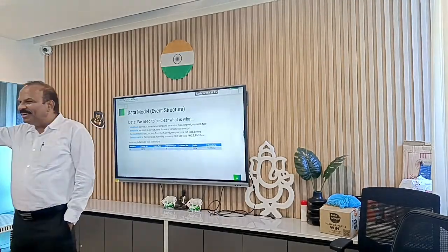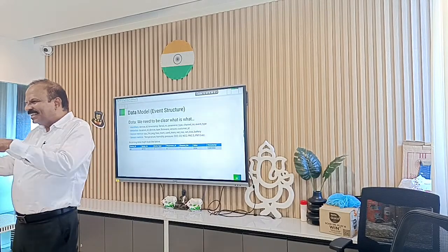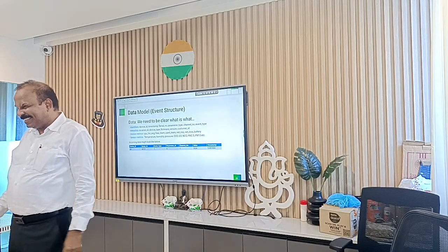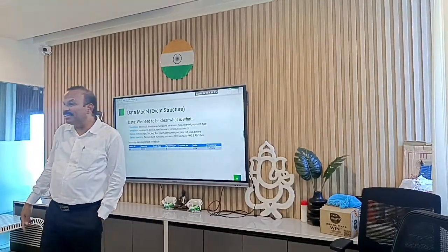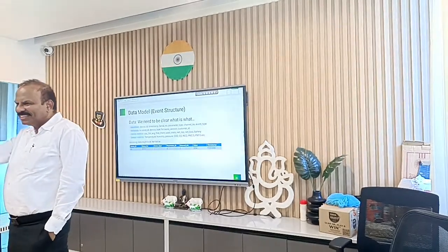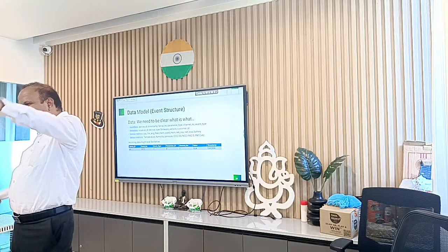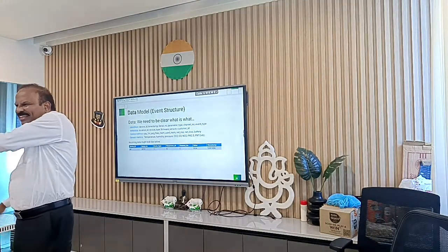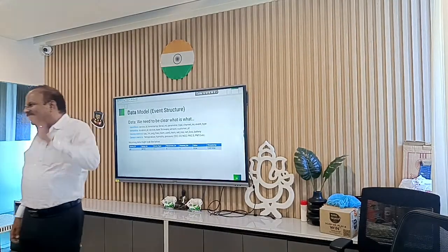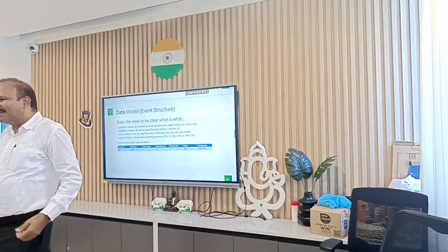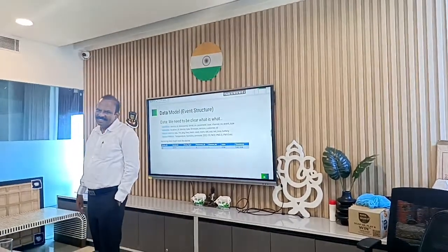Simultaneously, some new equipment was added there. They thought that the spare wire was spare, and they started connecting it. This is the one giving feedback to the station master. The moment that new equipment was added, this fellow gave an operational signal, and before he operated, that gave a signal through the new equipment, and he got a signal. Instead of the train going into the main line, it went into the loop line. Because of that.